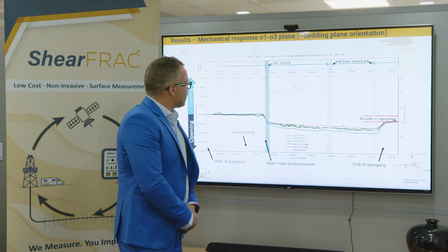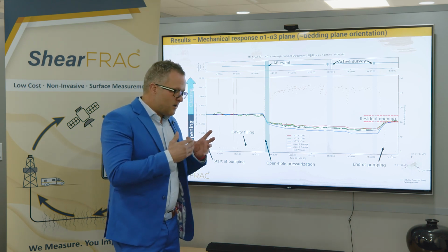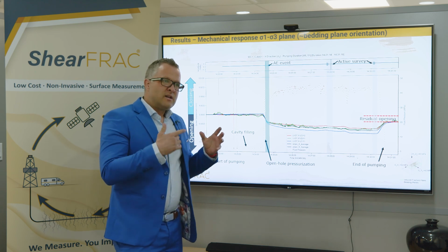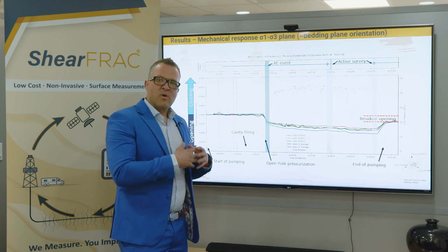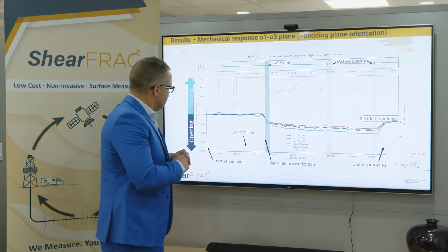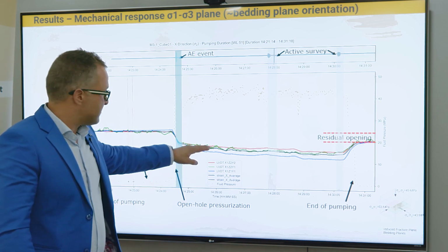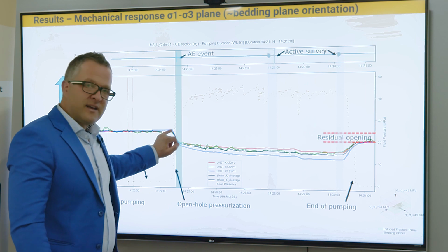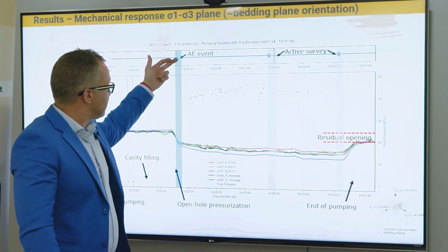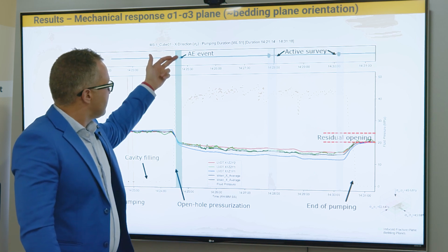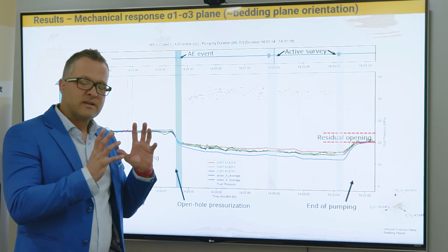As I move forward in the results of the experiment, once we take our machined cube, put it in our true triaxial load cell, inject slick water frac fluid, we want to mimic and see what an actual fracture stage looks like. You can see here we have LVDT sensors on this. So this is our initial static cube. You can see I've noted an acoustic emission event here. I failed to mention that this cube has 16 acoustic emission sensors wrapped all around it.